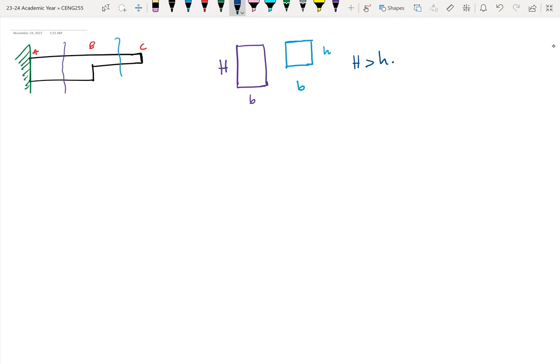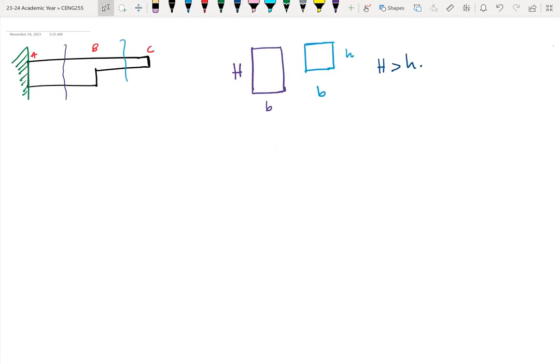So I can have this beam carry a load, let's say a load applied at C. Maybe in this case, it's a point moment. I'm pretty sure I might have mentioned this to you last time. So we have a point moment of 500 newton meters, or maybe 0.5 kilonewton meter, depending on how you want to look at it.